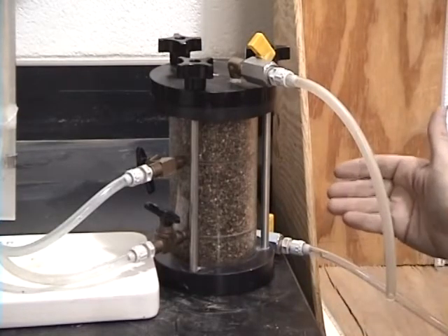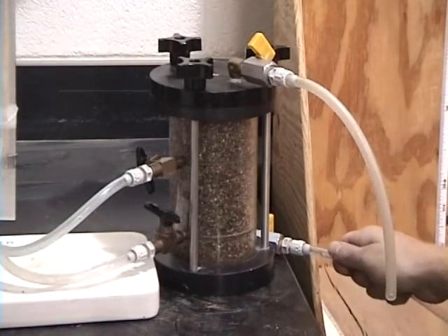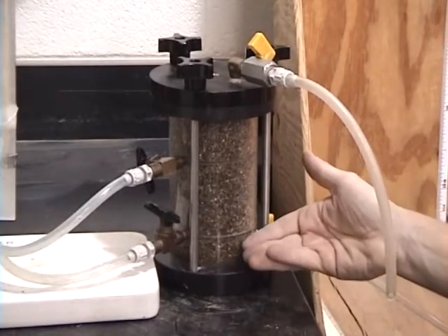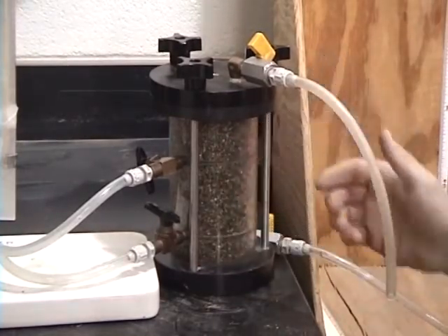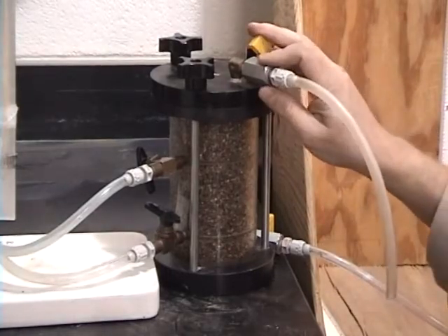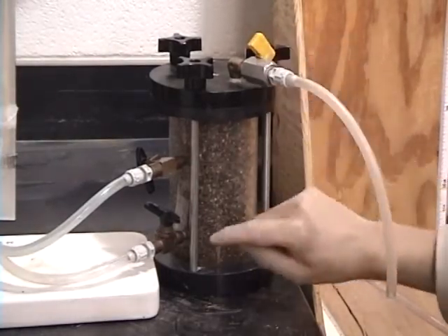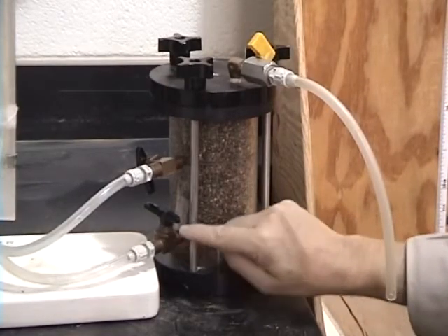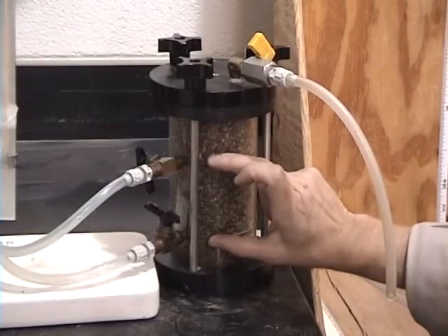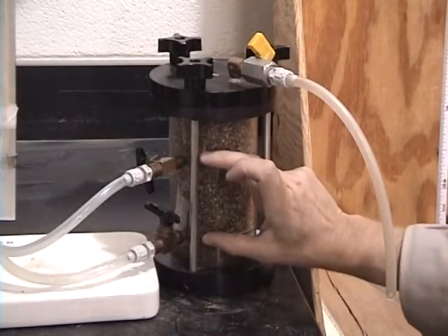We're going to be bringing water into the specimen through an influent port, which is in the bottom. The water will flow up from the bottom and out through an effluent port here, and we'll measure that flow volume. We have 2 ports along the side with some spacing, L sub C. That's the vertical spacing between these ports.